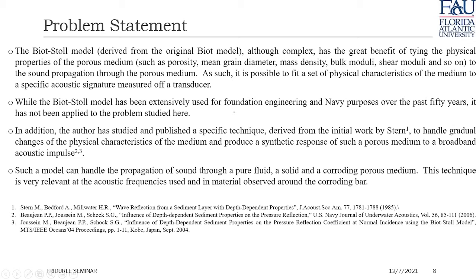So while the Biot model has been extensively used for foundation engineering, again, there remains in many ways a lot of work to be done with reinforced concrete. So what I propose is to use some of the specific techniques that I derived, initially inspired from the work of Stern, that include and account for depth-dependent properties within the medium, for example, increase in porosity or tortuosity with depth in the concrete up to the rebar, and see how we can, from there, infer a possible presence of early cracks.